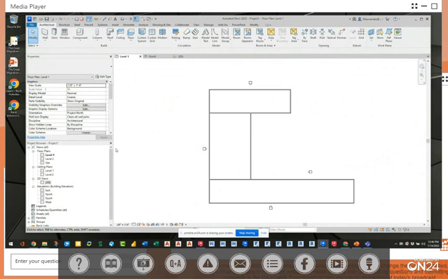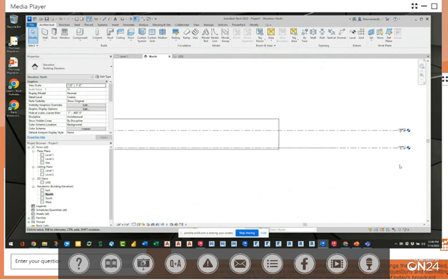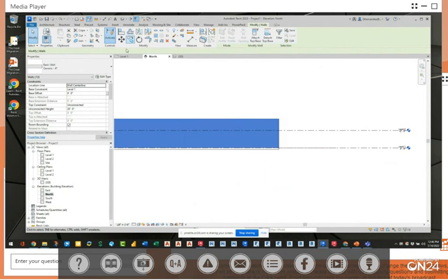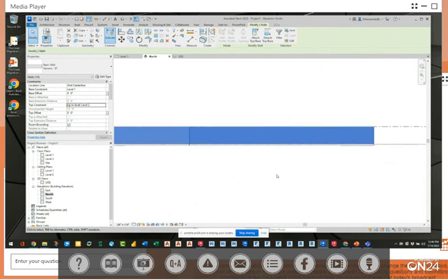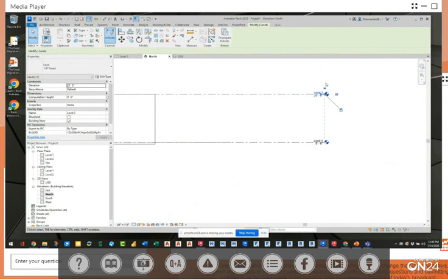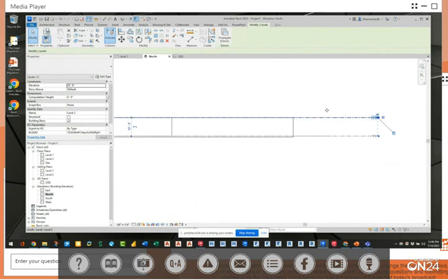And then if I come back and go to my level here, this is why the levels are so important. I set that to 12 feet, but everything that I'm building is beyond that 12 feet, right? So I could go in here and use my right-click method to select all of these walls, and then in the properties palette, I'll put those all to level 2. Now when I drag or move my level 2 to a different height, so maybe that, like I said, is 19.6 now, everything automatically adjusts so my walls stay put with the actual level.